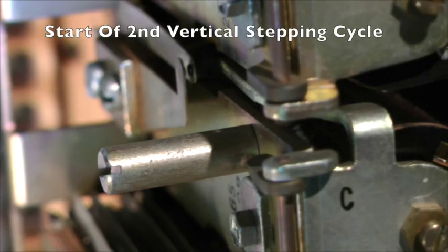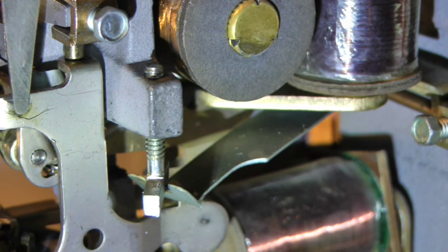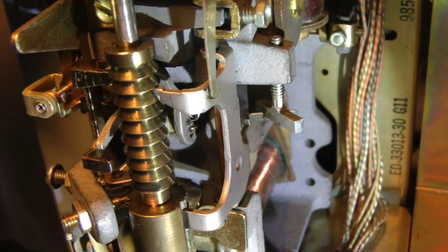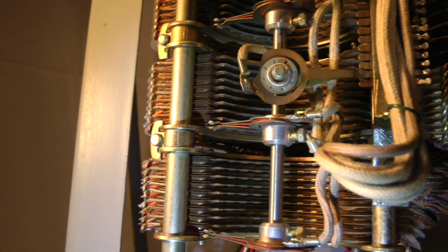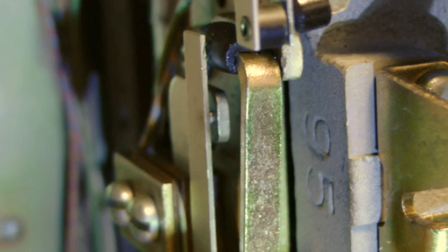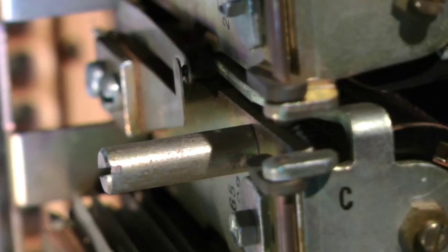The C relay reoperates. The vertical magnets are re-energized and the vertical armature operates. The vertical pawl engages the vertical ratchet and steps the shaft up by one step. The horizontal wipers step up to the second level, and the commutator wiper steps up to the second commutator segment. The vertical lever pivots, opening the vertical interrupter contact springs. The C relay releases.